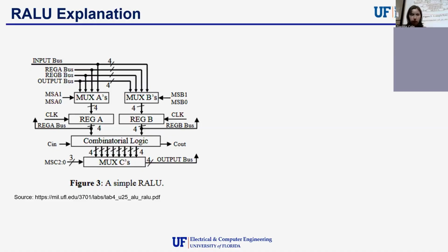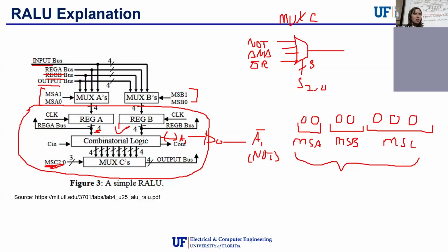You'll see later on, since this is a lot of different bits, there are ways to represent each instruction in fewer bits, but ultimately it's going to be translated into something like this, where you have bits multiplexing one register, bits multiplexing another register, there might be more registers, and then finally bits multiplexing the ALU part of it that is doing the instruction.